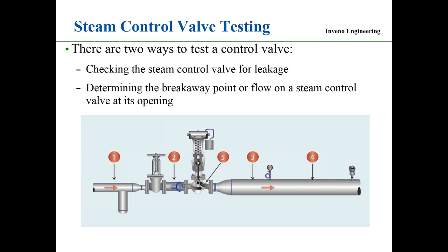The other thing is that we are looking at no component failures within 6 years of installation, period. The steam system, we cannot accept today component failures within 6 years. And internal leakage can cause issues in operation. So by doing this test, then we can determine what's causing it. And then the other thing about finding the leakage and everything else, root cause analysis, determine what caused the leakage to begin with, has to be part of the program. So anyway.